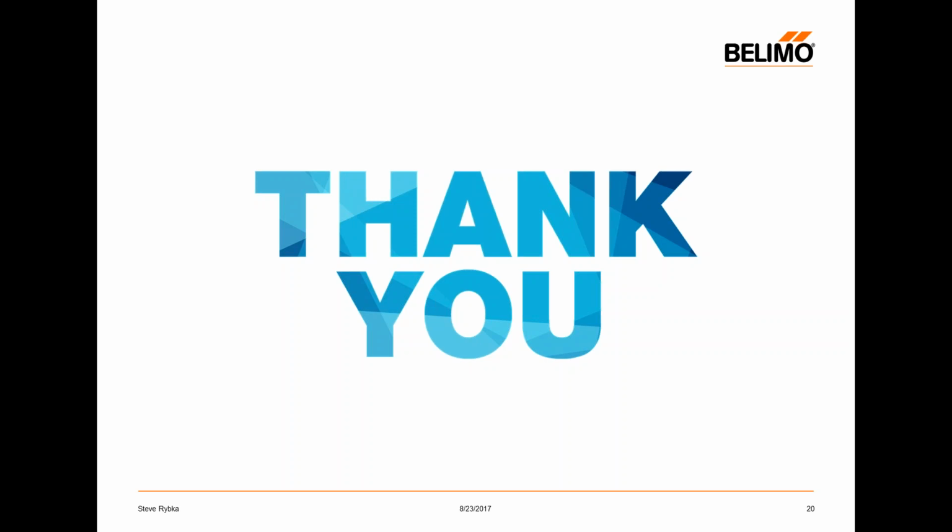Okay, the valve lowers the flow to increase the delta T. Is there a min flow set point in the flow? Okay, there's a couple things. There is a minimum delta T threshold. So there's a set point you can enter in the valve and say, at or below 30%, 10%, 20%, whatever number you select, the delta T manager will not engage. So that's one feature we have.